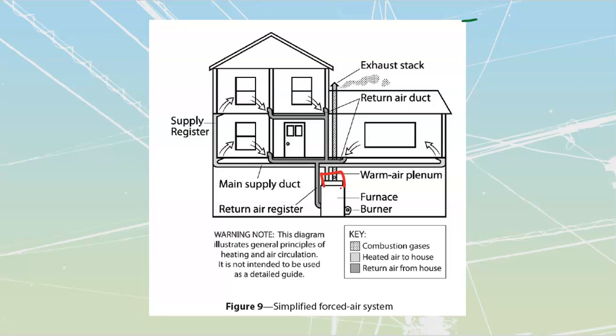A lot of people heat their houses off of fuel oil, kerosene still. They're going to have large tanks. They're going to get these things filled up every couple of weeks, and then they just burn that fuel to continue to heat their place. In some cases, if it's cold enough outside, the heat generated by the fuel alone is not going to be enough, and so we provide a secondary makeup type of heat, which is going to be basically electric resistance heating elements installed above there. They do not act as your primary source. They're designed to be used in conjunction with these.